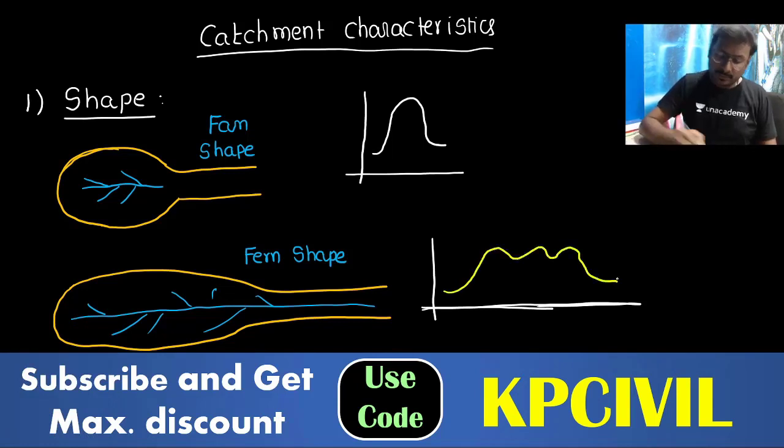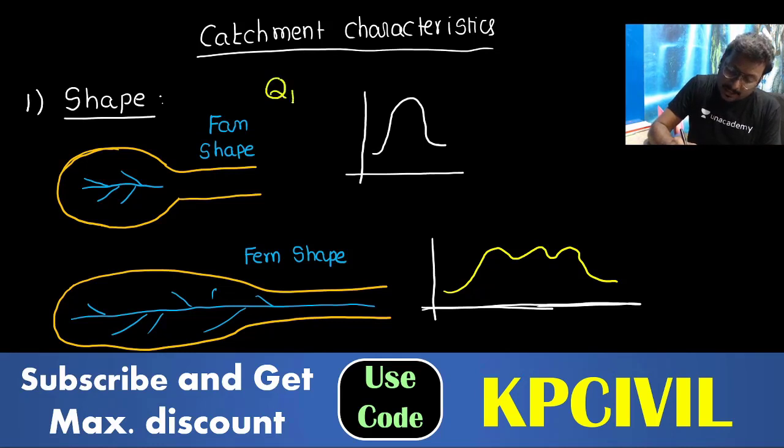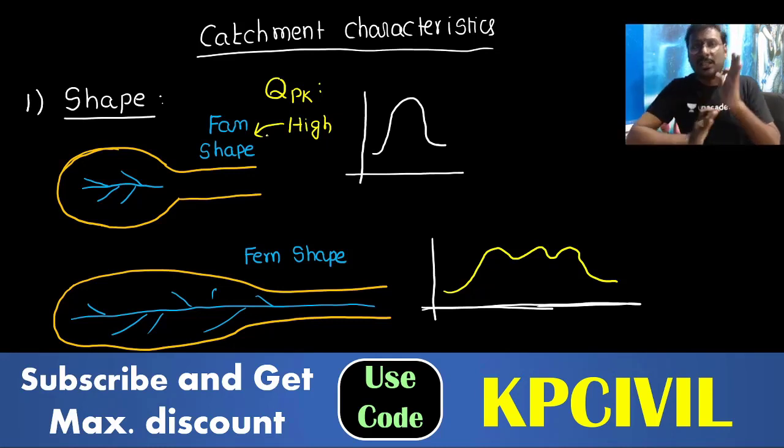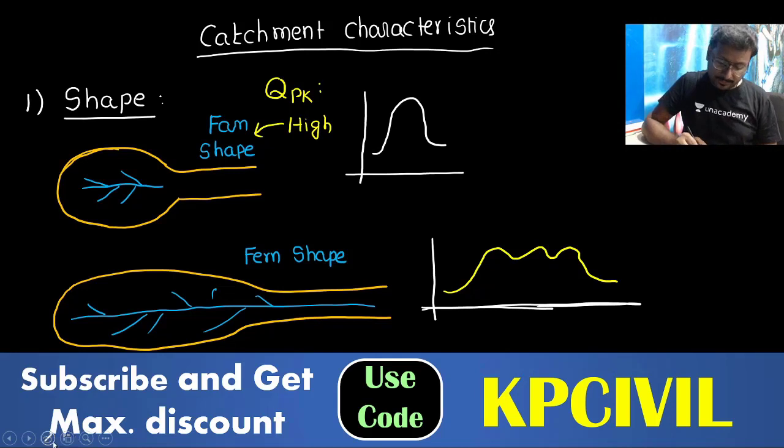The fan-shaped is carrying a higher peak. So peak discharge is high for fan-shaped catchment when compared with the fern-shaped catchment. So fan-shaped catchment is very much beneficial for the hydrograph.